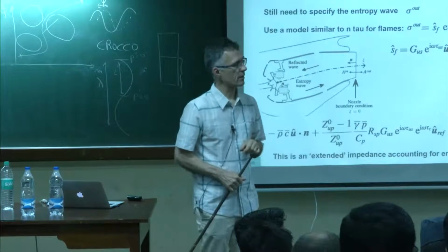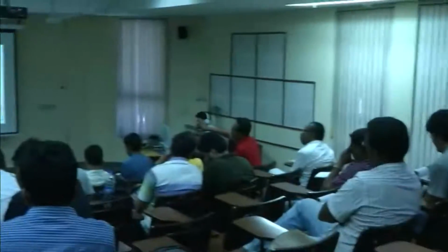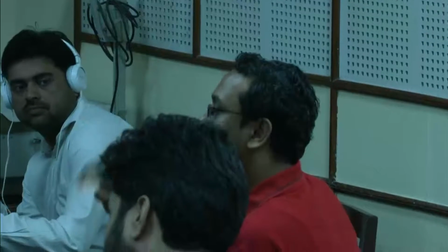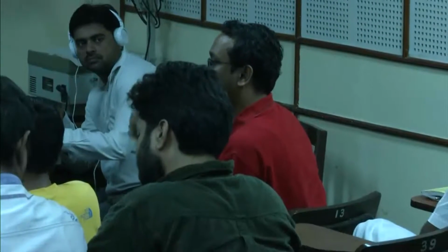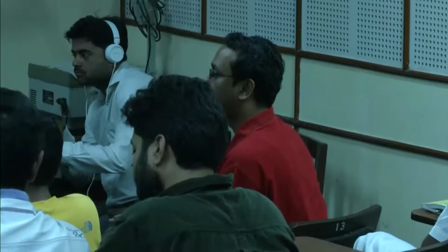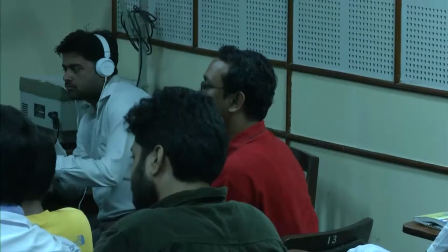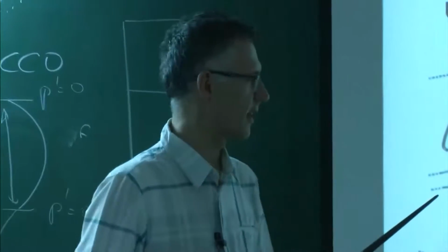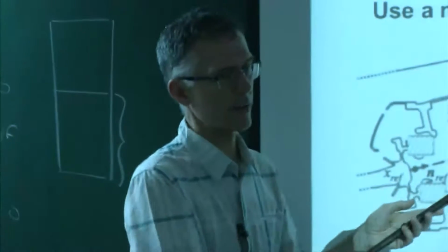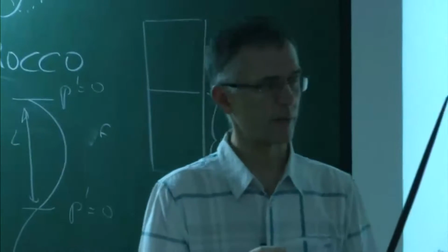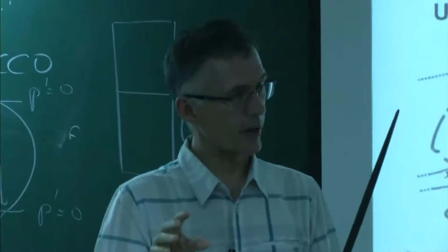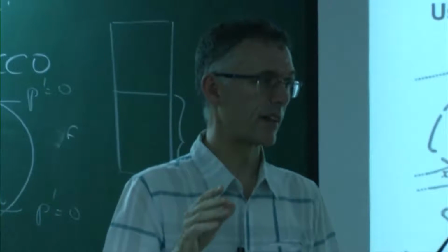In the approach we take, we solve for the flow first and then solve separately for acoustics. What could go wrong in that approach? Is it a good way to go? That's a good way to do it. But there are many small problems that you have to be aware of. Is that all the acoustic modes I'm describing here are for 0 Mach number. If you want to do what you said, you freeze the flow and you go for the acoustics, you have to say if you do it at 0 Mach number or not.